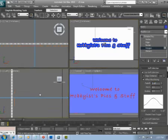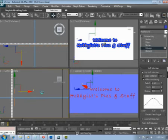So right-click in the left view, hit W to bring up the Move gizmo, and with that yellow horizontal stick, let's click, drag, and release. Now we wait.